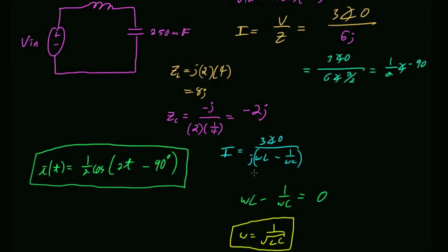It's a resonant circuit, and you're hitting it at the resonant frequency. That's what that means, right? So that circuit has a resonant frequency, and you'll be stimulating it at the resonant frequency, and that current will just keep getting bigger and bigger. It's like pushing someone on a swing, right? You're always pushing them in phase. They get higher and higher. At some point, some practical limitation breaks, like the kid falls off the swing, or the voltage source can't actually provide 10,000 volts of AC power. But mathematically, in theory, that's what happens.